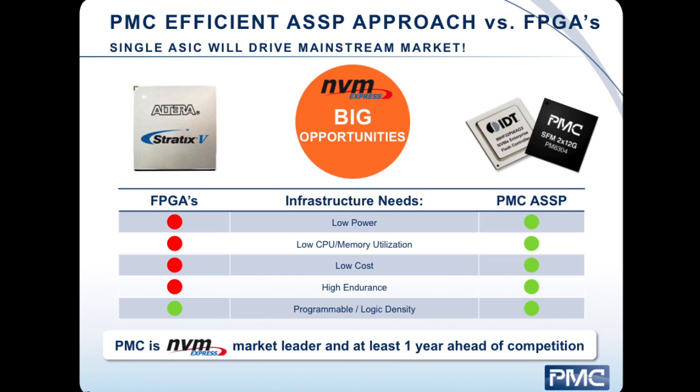The overhead, or the processing power required to run all the error correction in order to have data that's not going to get corrupted and destroyed, would use roughly about 80% of a Virtex-7, and that's a $1,500 chip. So it's just not a scalable path to use NAND with FPGAs.